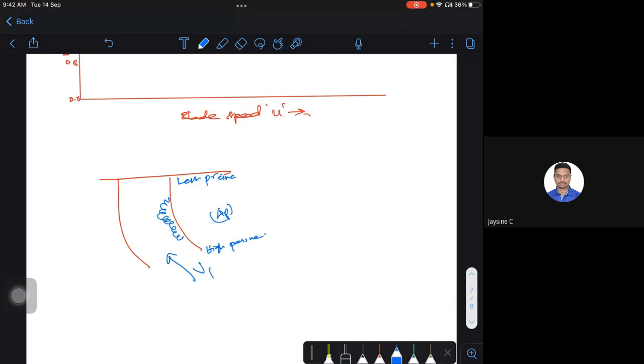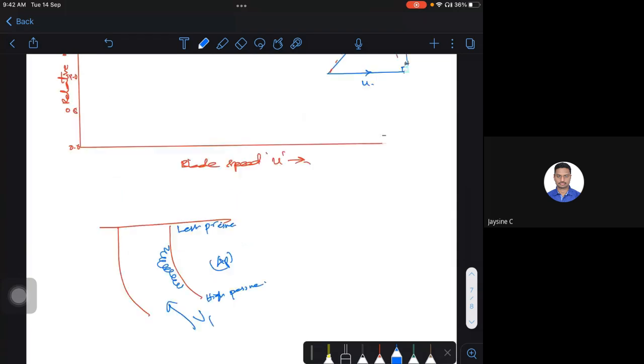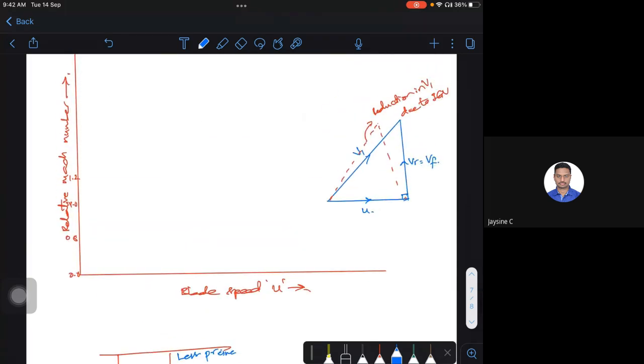There are situations where the blades fail because of the shock. If there is a formation of shock there, there is always some kind of damage caused to the blade. To avoid all these things, they include or add these inlet guide vanes, or IGVs, at the entry to the compressors.